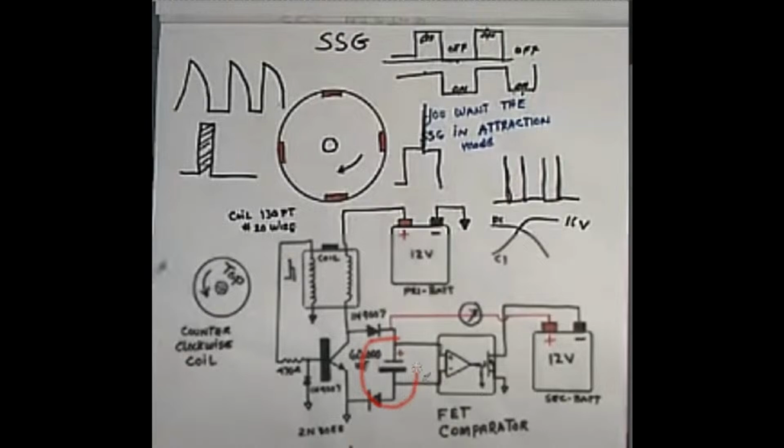across this capacitor in the linear amplifier regulator, and he's doing it using these two flyback diodes. They're both high voltage, and he used them because after he sends the constant 12 volts into this capacitor, it stays constant even during the flyback, which I think is pretty handy. So you keep the potential there on that capacitor. And mind you, once this capacitor is charged, it's not going to interfere with this coil and the field generation, because it's no longer creating a load on this coil, and it just won't create a field either.